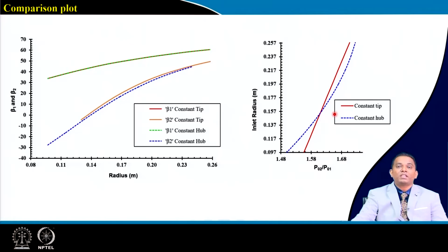And finally, as per our engine configuration, we need to be very careful. We are talking about design for a single stage at this instant, and we know our compressor for an aero engine, a land based power plant, or the process industry is made up of a number of stages. It's a multi-stage axial flow compressor, and for that you may need a number of design iterations, where your understanding and expertise will help reduce the number of iterations for the design.